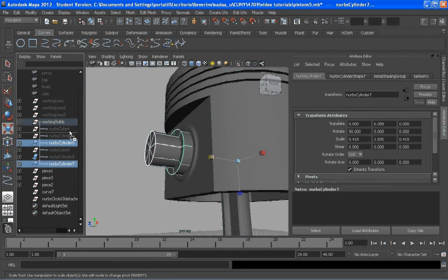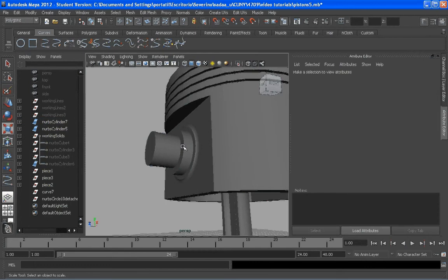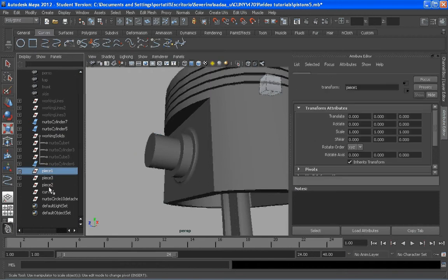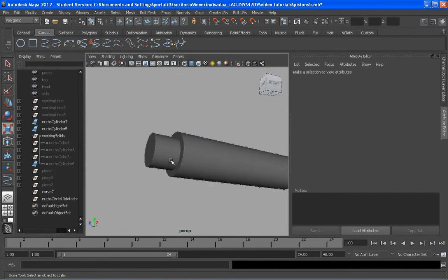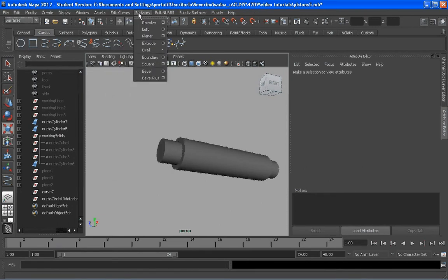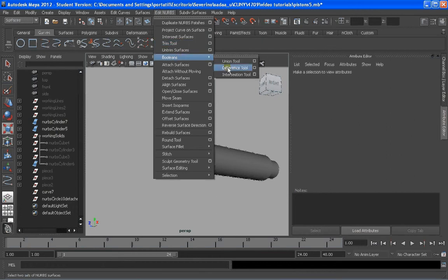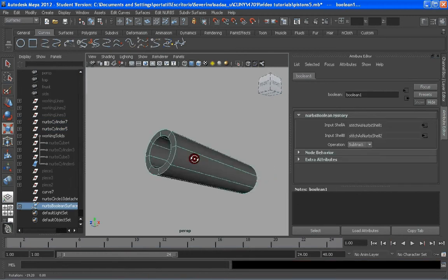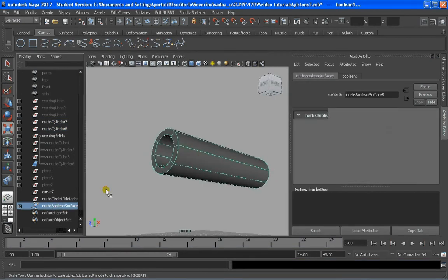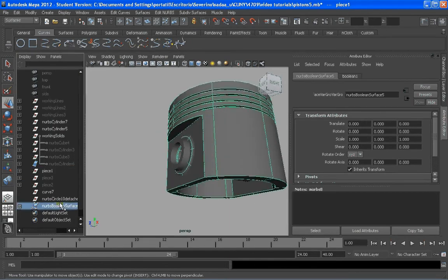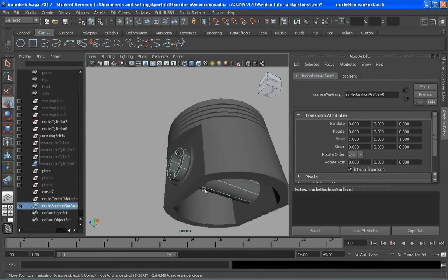And now we're going to be able to do, let's see it more carefully because it's probably difficult to see. Let's turn off these guys, and now let's do in surfaces, curve the surface. Sorry, inverse Boolean difference. This one, enter. This one, enter, and it creates the cut. Now that becomes the inverse Boolean surface that we can select here. And if you turn on the piece one, Shift H, and select this guy, you're going to be able to move it.